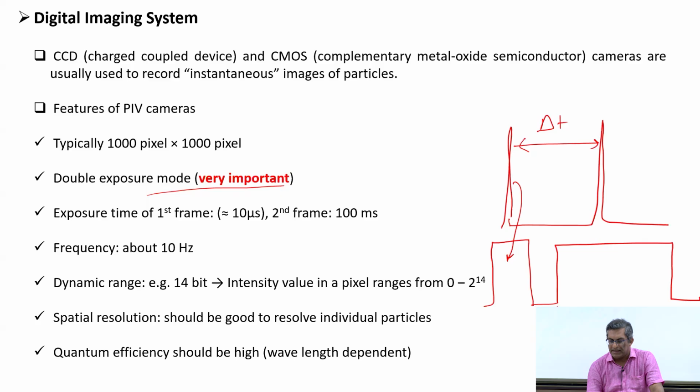So, the camera shutter opens such that this image is read, then the camera shutter opens again. Typically the shutter opening for the second time is longer because it needs some time to read both the images. But as I said, the camera opening time does not control the image, rather the laser pulse duration controls the image.